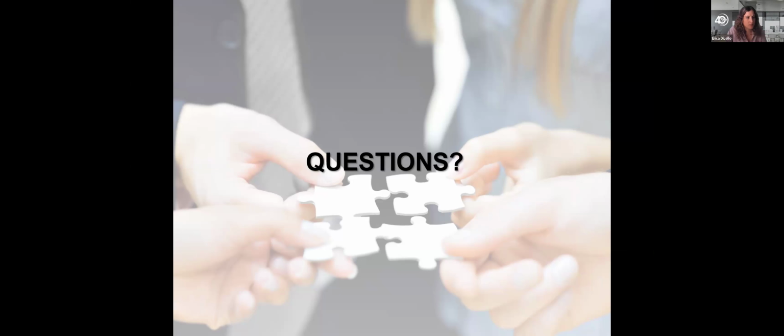Thanks, Ken. Okay, is it better to size the heat pump for cooling so it's not oversized and use supplemental heat during heating when needed? Yeah, so I didn't really get into that. There's a whole procedure in the manual for when you're using, say, a variable heat pump, for example. There are cooling limitations to that as well. Depending on where you're at, what your zoning is, and how much heating you have, oftentimes, if you're in a somewhat mild climate, you would size the heat pump for the cooling load, and then you would use supplemental heating for your additional heating load.